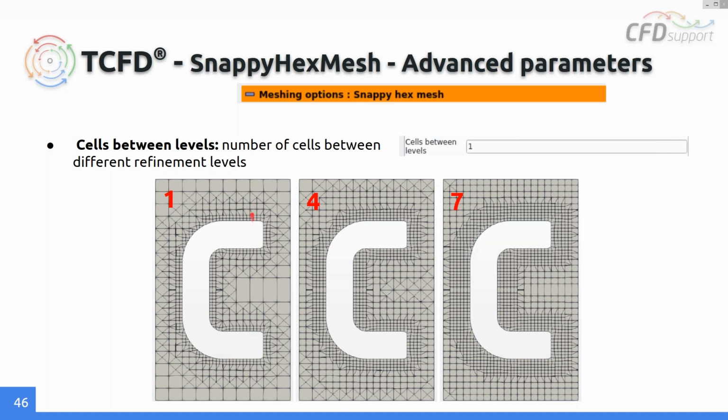But if you use, for example, 7, the transition from the finer mesh to the rough mesh is much smoother. Of course, you have to count that we are always in 3D, and it is really hungry for cell amount. The mesh is then much smoother, finer and nicer, but you can get a lot of cells.